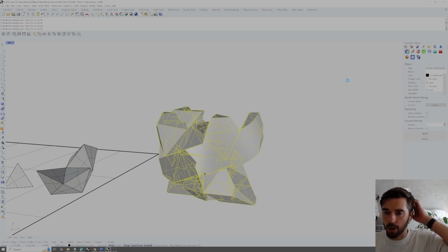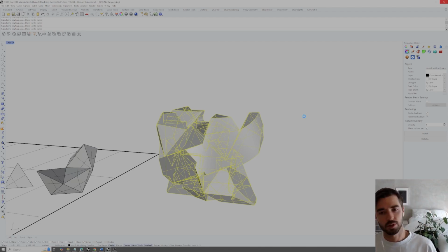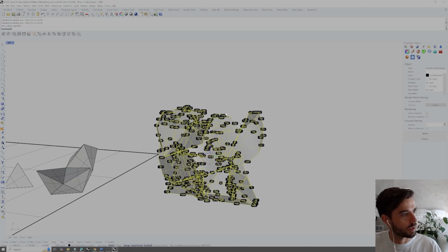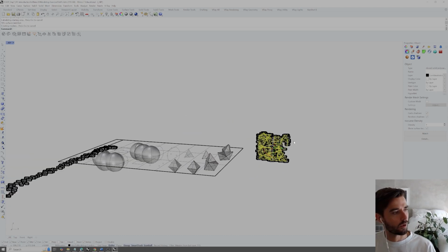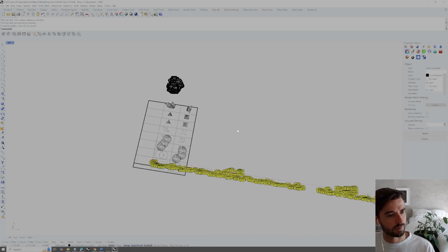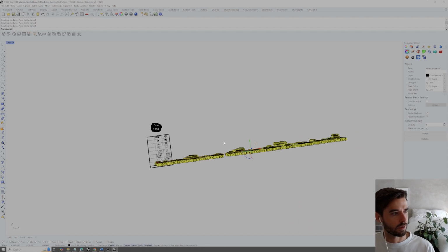And I'll move the output of this up to the combinatorics layer so that we can kind of see that relative to our unrolled geometry. Now, some of those edge fillets, if they're happening on curved surfaces, which I don't believe we had any that were, it would give us an error saying that it had an issue making that, but we shouldn't have any as of now, because we are using singly curved geometries.